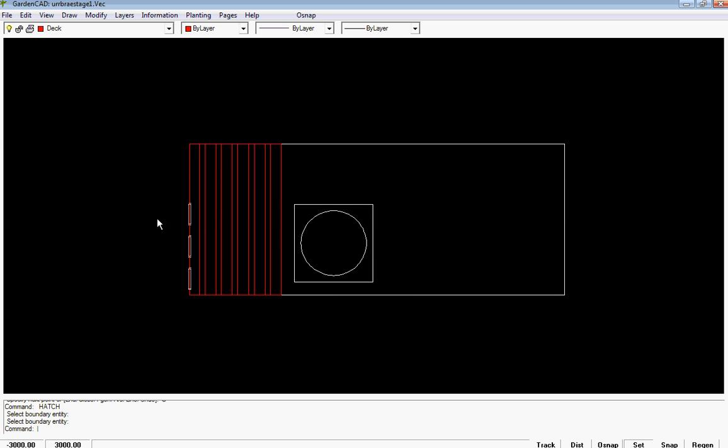So now from the house here with 3 windows looking out onto the deck area, we'll organise a step down, and this will be the paving area. So the red lines represent the decking, and you might even want to change it and make the scale factor a little lower, maybe 1000, to give you some more closely spaced lines, but that's up to you. We'll put some text on there later to indicate that's a paved area. So there'll be some double doors opening here onto the decking and then stepping down into the adult entertaining area with a tank underneath it.